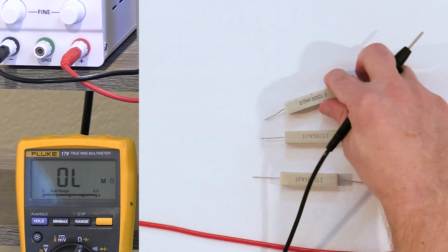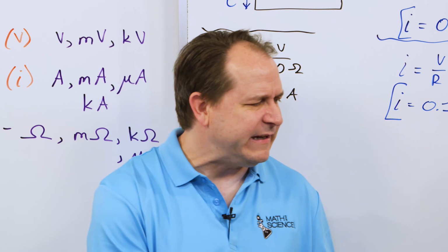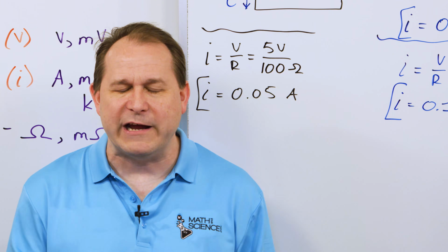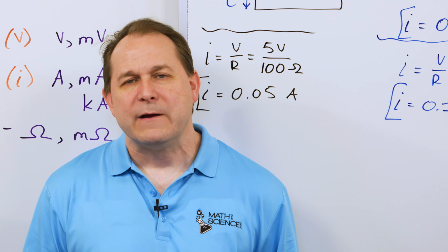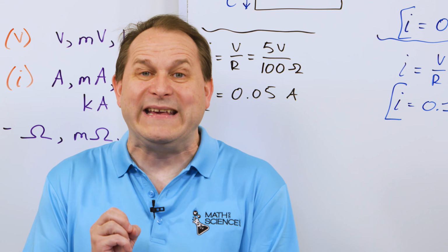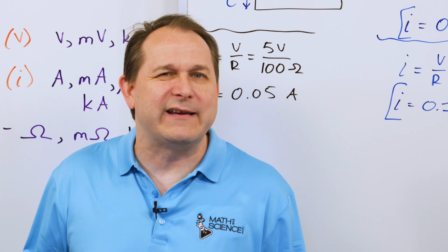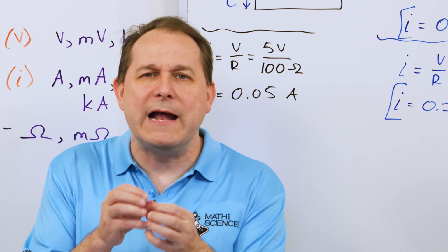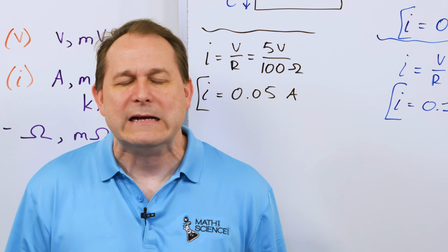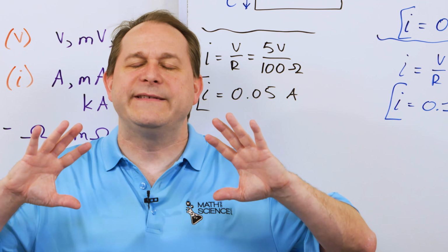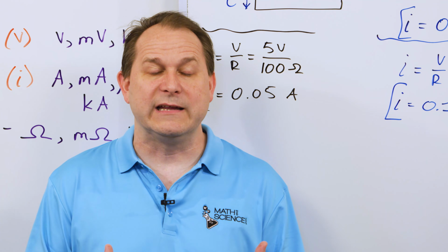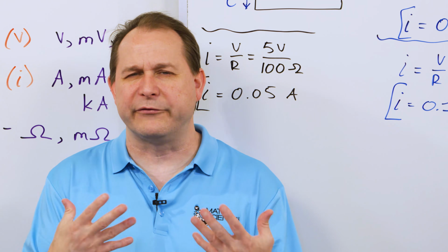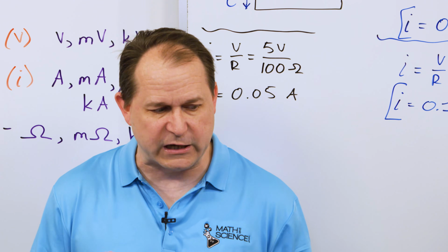All right, now here's the other little wrinkle here. I'm teaching you that these resistors are constant values. These resistors are constant, right? They don't change. In reality, everything changes, right? And so as these resistors heat up, the resistance changes a tiny bit. Same thing with light bulbs. As the light bulb gets physically hot, the resistance value can change a little bit. But we ignore that and we say that these resistor values are constant unless you're trying to do something extremely precise, where you have very accurate measurements. We just assume that everything is constant here.